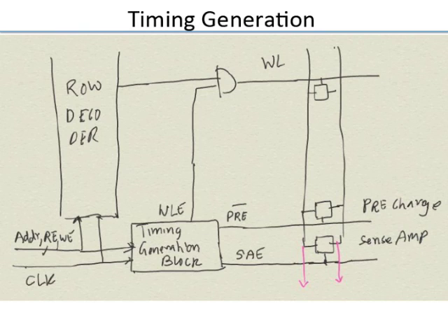So how then do people do pipelining? How do people pipeline the memories? Well, you use what are called pulsed techniques. We'll see that probably in the next class, where there is no pipe stage, but internally you have pulses which are flowing through. So you can have multiple pulses in transit.